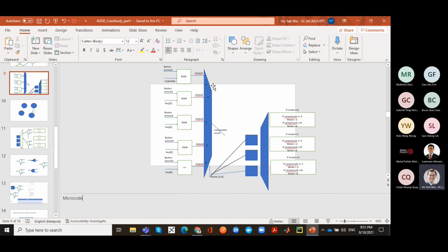Well, one would be in the debugging and the testing stage. Like you're not quite sure the design meets all the specifications. It's a very complex set of requirements. So you can implement the desired logic as a microcode, test it out in real circuits, and then if it doesn't work, you can change it slightly, and you don't actually have to build a new chip. So this is one reason why we might want a solution like this.